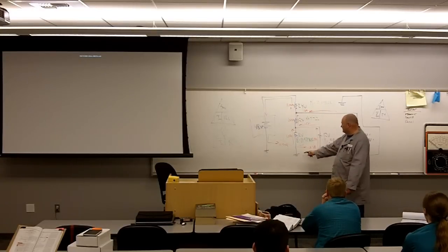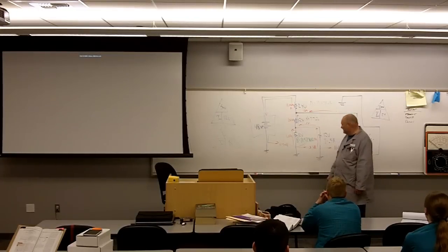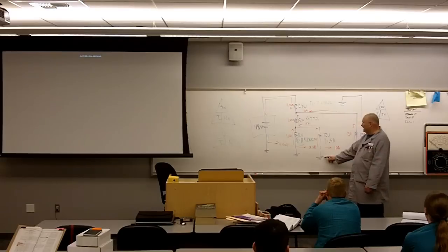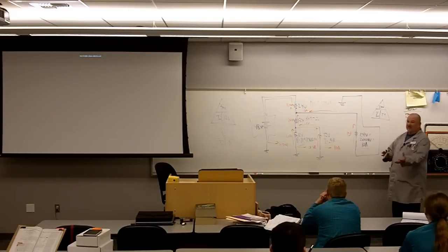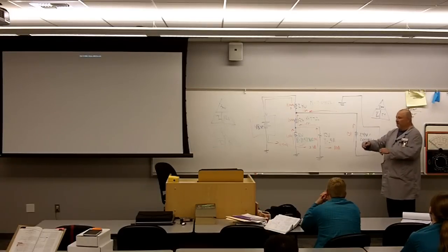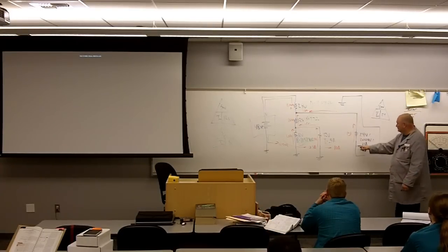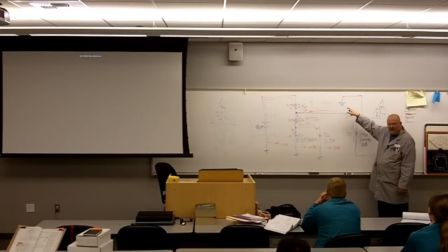We're going to get the bottom of the circuit here, the bleeder resistor, and connect that also to chassis ground. Okay? We're going to connect the negative lead of our radio directly to chassis ground. We're going to connect the negative lead of our radar. The radar's mounted in an unusual position, you know. I've got the pulpit up there, I drive the boat, I want the little radar there. So I'm going to have to run quite a bit of cable, but I'm still going to connect it to chassis ground.